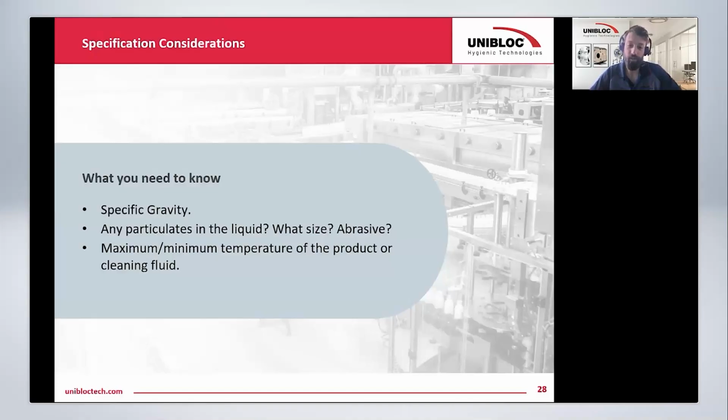So just knowing what your application is, and then as much detail as will be needed to make sure we can accurately size the pump for you. So if there's solids, we'll need to know what those are. And then cleaning considerations are always important. How are you going to clean the pump? Because that can make a big difference on how we spec it.